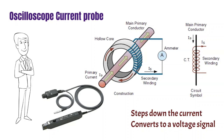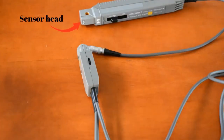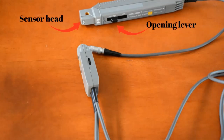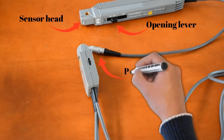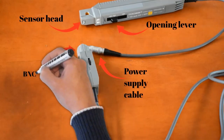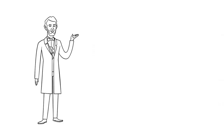Let's identify the parts of the current probe. First, you can see the sensor head. The conductor goes through this sensor head. It can be opened using the opening lever. The current probe is powered through the power supply cable. We use a BNC connector, as with the voltage probe, to connect the current probe to the oscilloscope. These few parts are sufficient for you to know at this level, but if you are interested, you are most welcome to search. Now you are familiar with how to measure a voltage waveform.